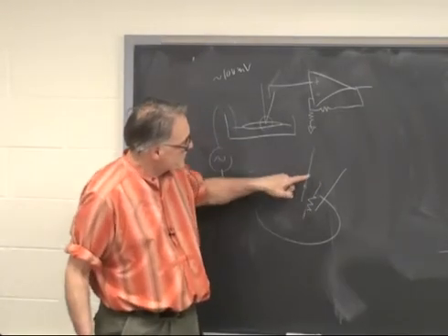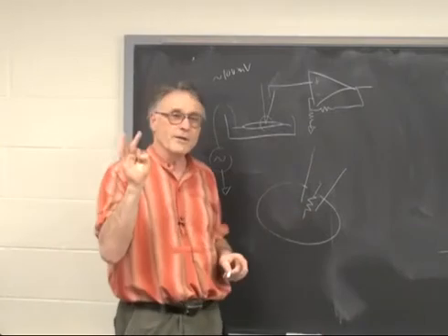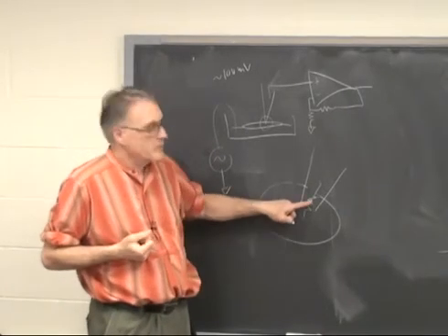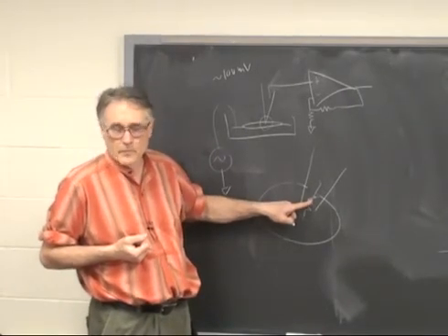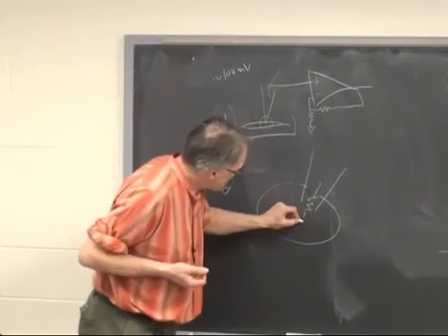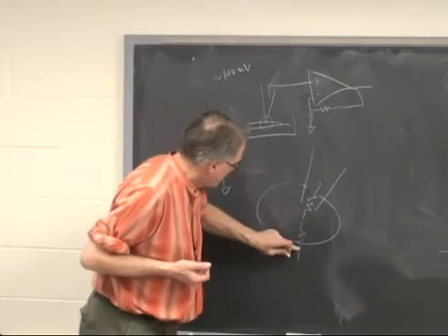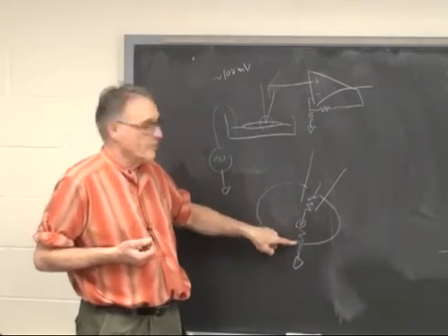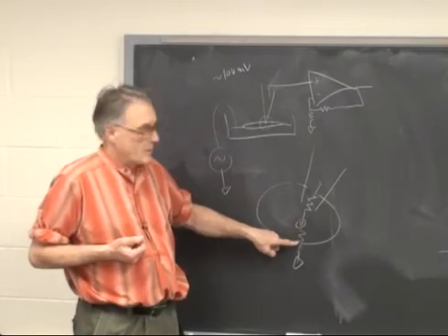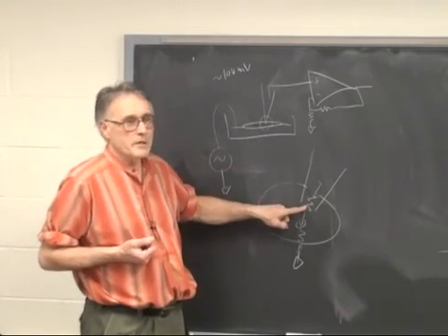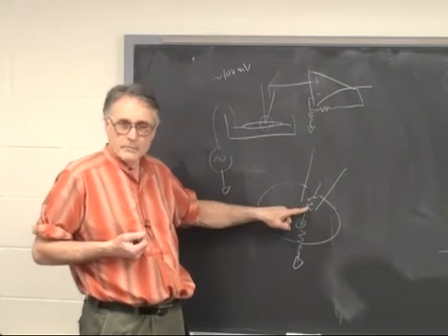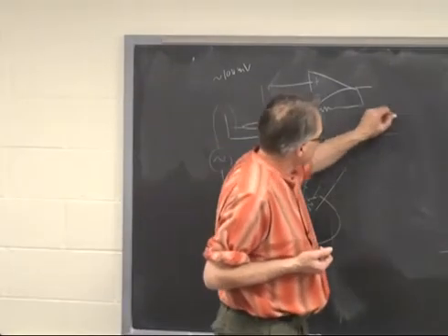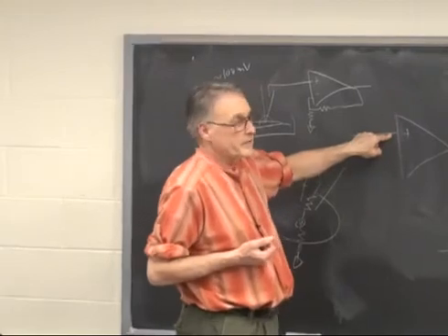So there's some series resistance. As you drop this aperture down to a wavelength of light or so, the conductance path gets small, and so the resistance must get large. And there's some small series resistance out of the cell with some sort of voltage source here to ground, and this is kind of the Thevenin equivalent voltage source you're trying to measure. So you have a very high resistance here. That's okay. That's good. That makes it a good voltmeter. Right? High resistance is good for measuring voltages. And we go up to this electrometer amplifier, which draws almost no current into its input.